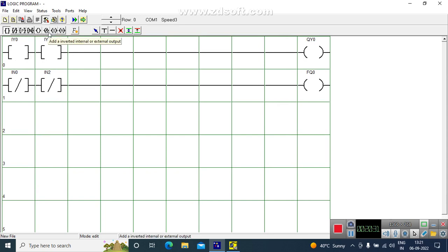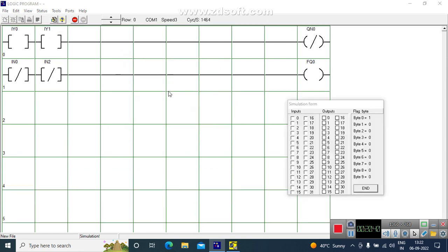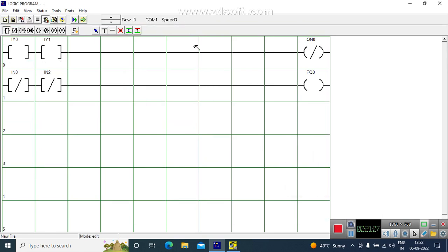Now this is nothing but a reverse contact. Okay, I can add a reverse contact here and show you. Say output 0. As you run, you see it's a reverse contact. That means input 0 not energized, output 0 energized. So this works as a reverse input. Okay, so even in the contacts, as I said, you have normally open, normally close, and output relay contacts. This is for the inputs, this is for the outputs. So let's start. Okay. We'll come back to this later on.